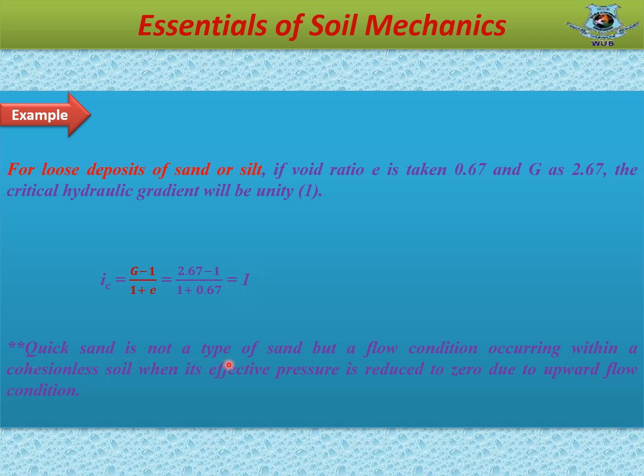Quicksand is not a type of sand, but a flow condition occurring within a cohesionless soil when its effective pressure is reduced to 0 due to upward flow condition.